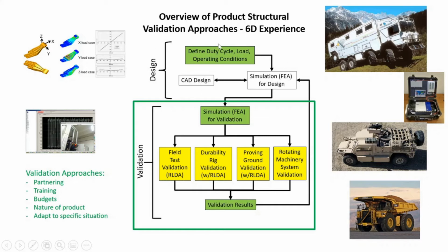Our customers generally handle the design aspects of the product. We really don't get involved too much in the design. But we do sometimes help on the front end of defining duty cycles, loads, and operating conditions. For example, turning a part into a load cell, taking data out in the field where there might be a very special, important loading condition. Sometimes this data is acquired over a long period of time, looking for maybe rare, large, significant events.